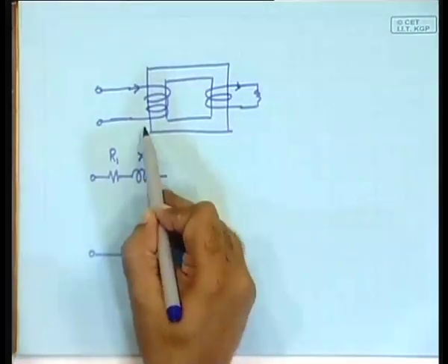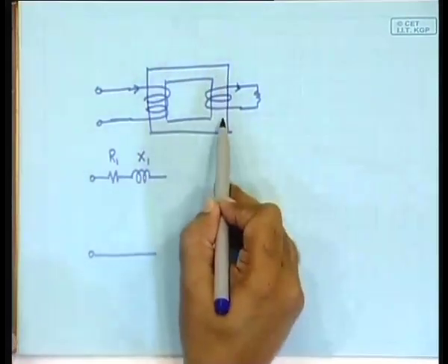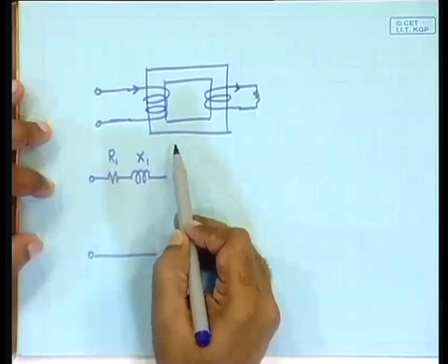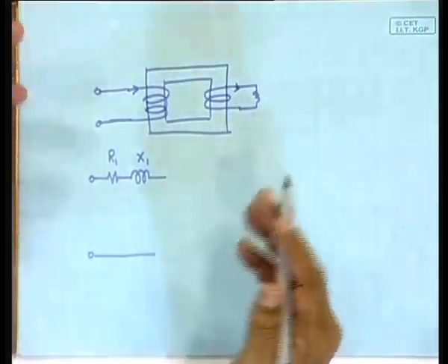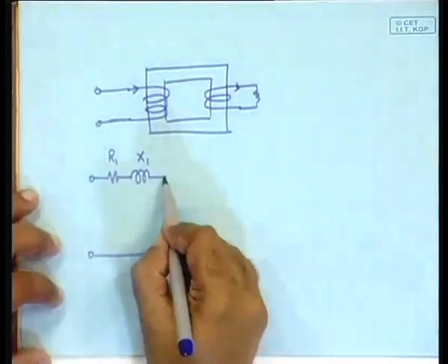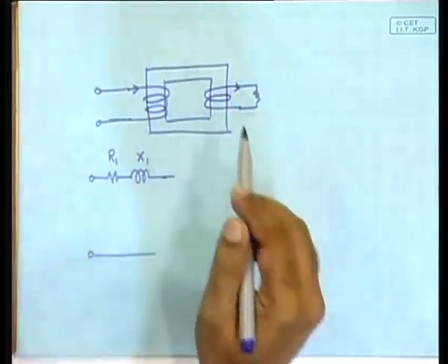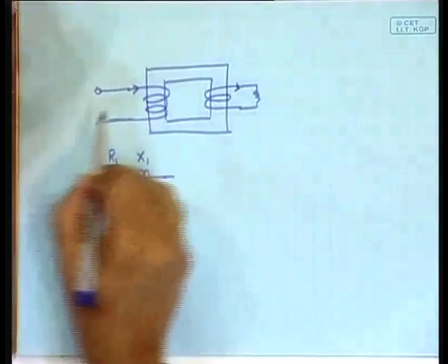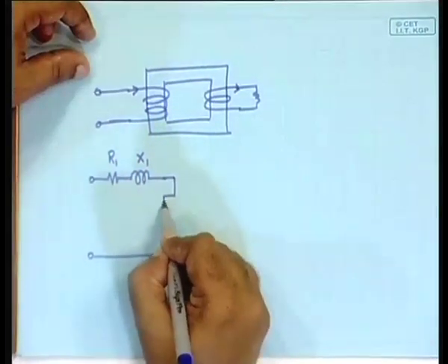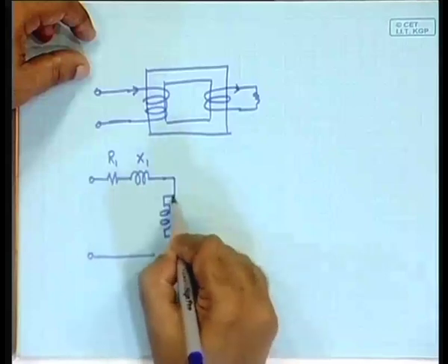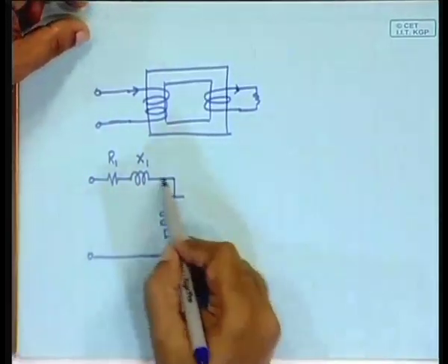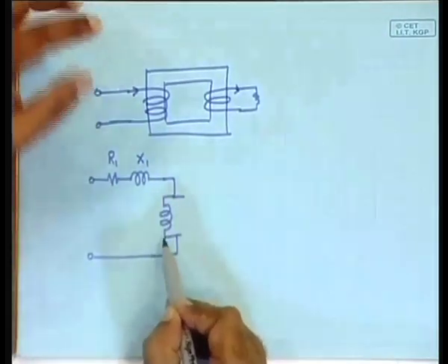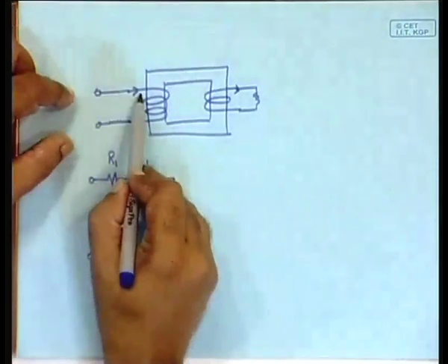and then there is a magnetic circuit. What does the magnetic circuit do? The magnetic circuit, of course, in order to establish the magnetic field, you have to spend. And in what way is it spent? There has to be some kind of an impedance that is seen by this stator side. It is represented here, and it is like this. So there is an impedance that is seen through this, whatever the current is flowing, that is representative of the component of the input current that produces the magnetic field.